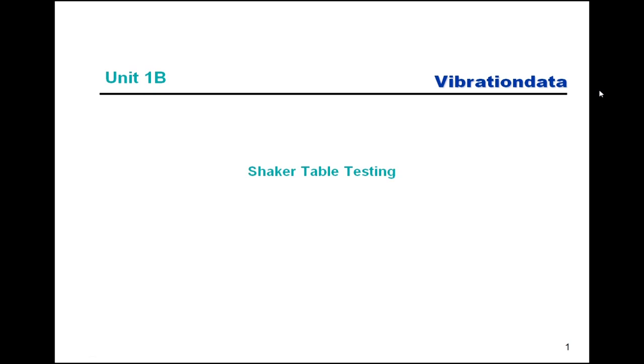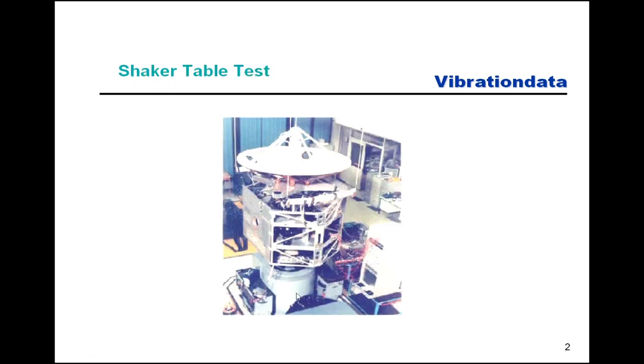Even for large shakers, sometimes scale models of buildings will be placed upon them for an earthquake simulation test. And these are done on shaker tables. The most common one for avionics components is an electromagnetic shaker, also called an electrodynamic shaker. Sometimes we test things as large as satellite payloads or space probes. Other times we test things as small as a little RF coupler or RF splitter or divider that's not much bigger than a book of matches, and everything in between.